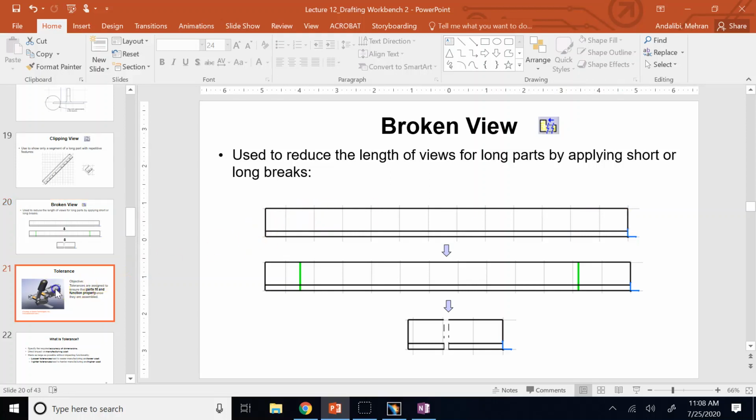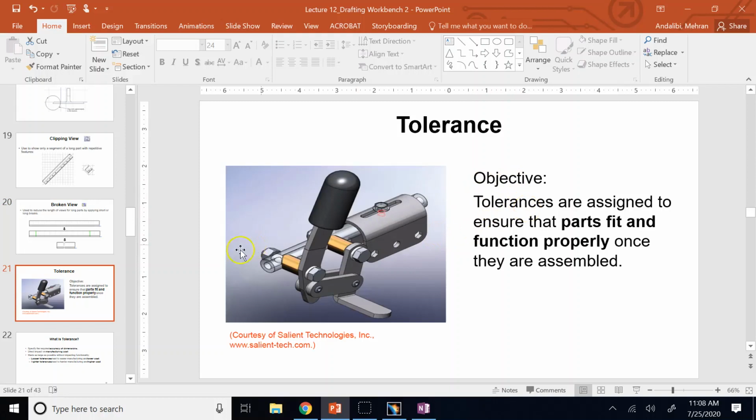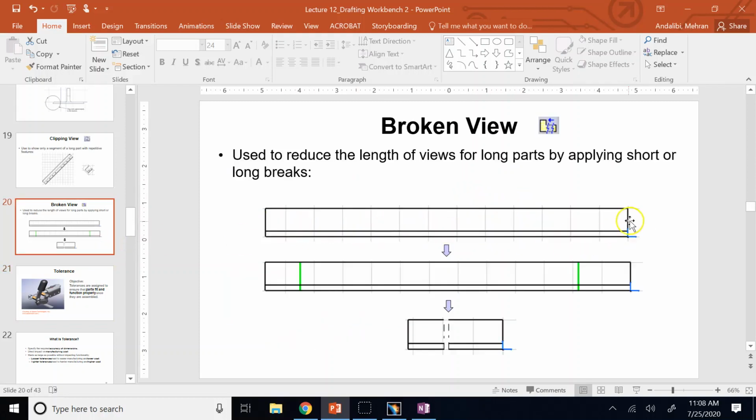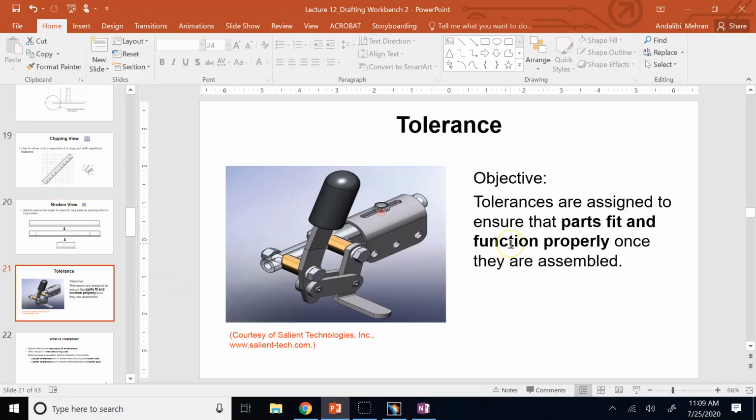But why don't you make the tolerance as tight as possible? So if this is 1, why don't you ask the manufacturer that, hey, the maximum error that I allow you to have is 1.00001 instead of just saying 1.01? Why won't you add more and more decimals to make sure they are closer and closer to what you want? Yes, because having tight tolerances means they have to use more accurate machining and more accurate devices to measure and check, and more time to hit that tolerance.